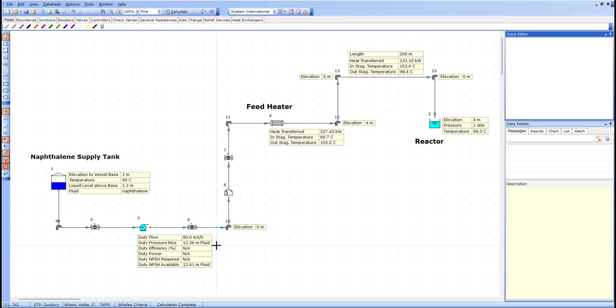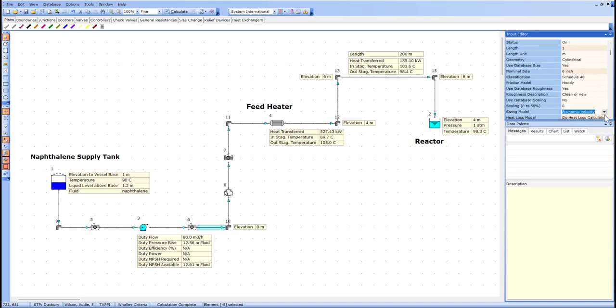A good starting point is sizing the pipework using economic criteria, balancing installation cost, operating cost, energy consumption, and maintenance. Then decide how you'll control the flow rate with a control valve or a variable speed drive. In this example, we'll use a variable speed pump because it reaches the duty point directly instead of wasting excess pressure through throttling. Once the design flow rate is set, FluidFlow can evaluate the system losses and help size the pipework. To automatically size the pipes, FluidFlow offers several options, including economic velocity, design velocity, and design pressure gradient. Here, we'll choose economic velocity to develop the most economical design.